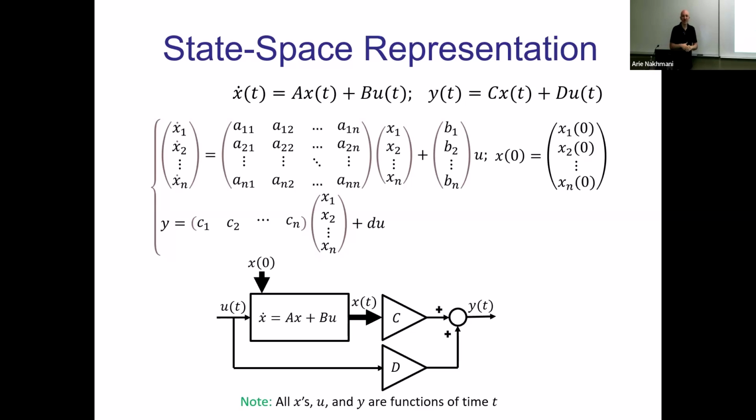And this is how you represent that with blocks. So I showed you already an example online. I published an example online of how you develop block diagrams for any given system in state space. Okay, you're just drawing all kinds of integrators and so on. But here we want to combine multiple integrators in the same block. And we can use that type of block, which is x dot equals Ax plus Bu. And this block generates vector x. And by a bold line, I define a vector instead of a scalar, right, for the SISO system.